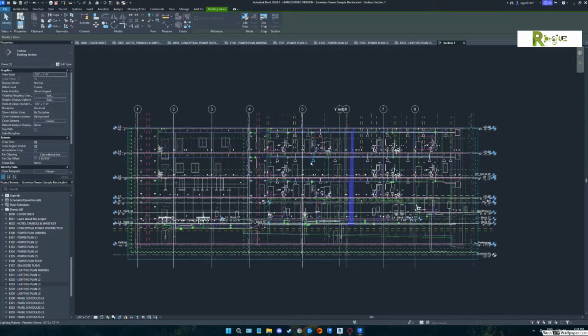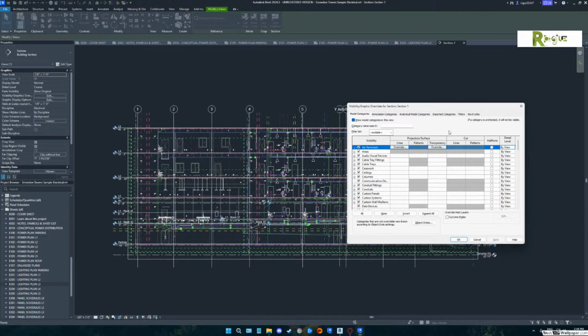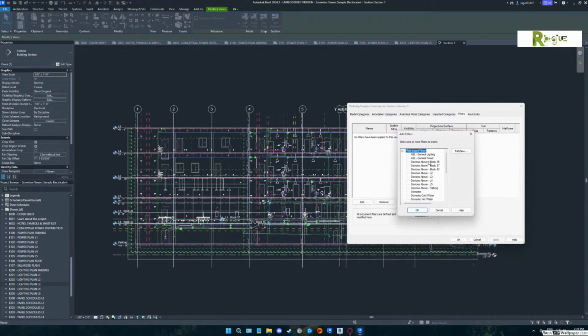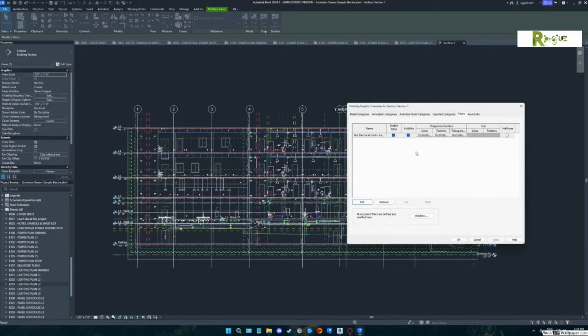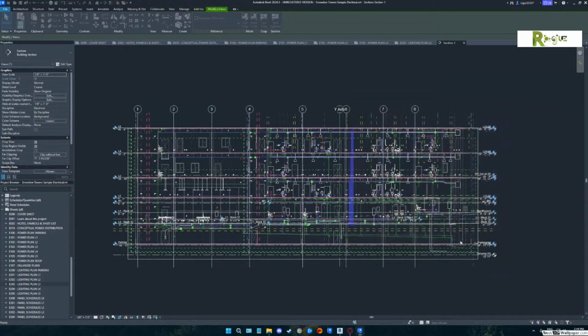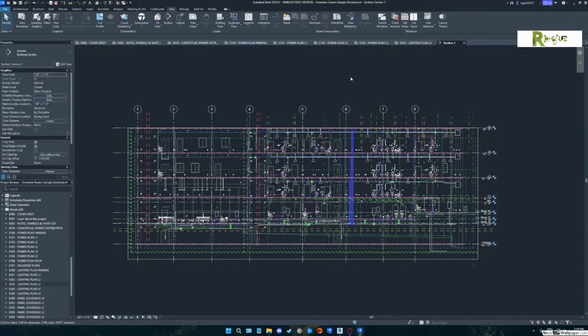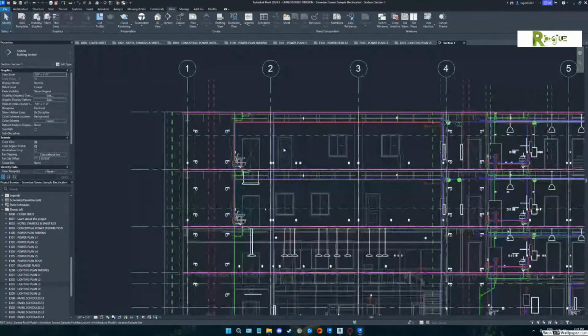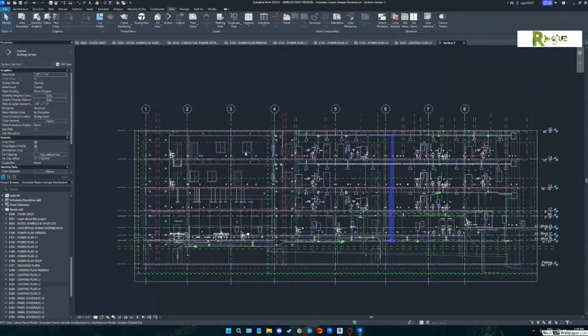Do me a favor, do a VV and show me all your filters that are in this file. Say add. And that's going to show me all the filters that they've actually got. So do they have not electrical grids? By putting that on and turning the visibility off, you would take care of that problem that we were just talking about. You should now see dashes in all the lines. See how much better it looks? Yeah. They just never applied that.